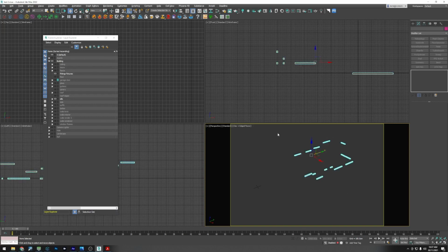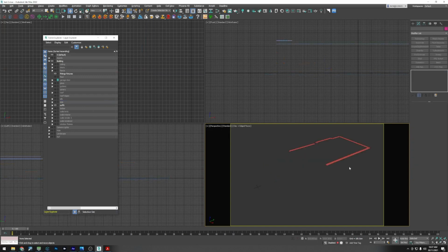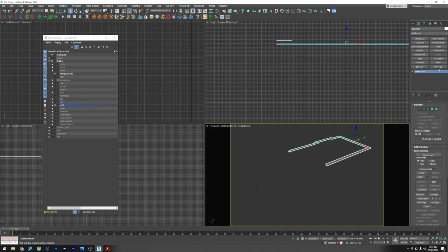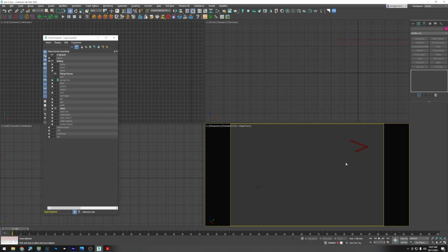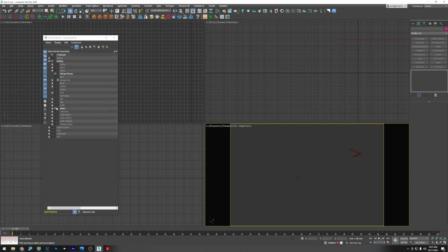The sills, again, they'll probably be a render color, so we'll throw a UVW box map on those. The slab, same thing, just a quick box map, otherwise they look fine. The soffits, again, exact same thing, just drag a UVW box map onto them. Same with this timber, UVW box map, that's all we need to do.